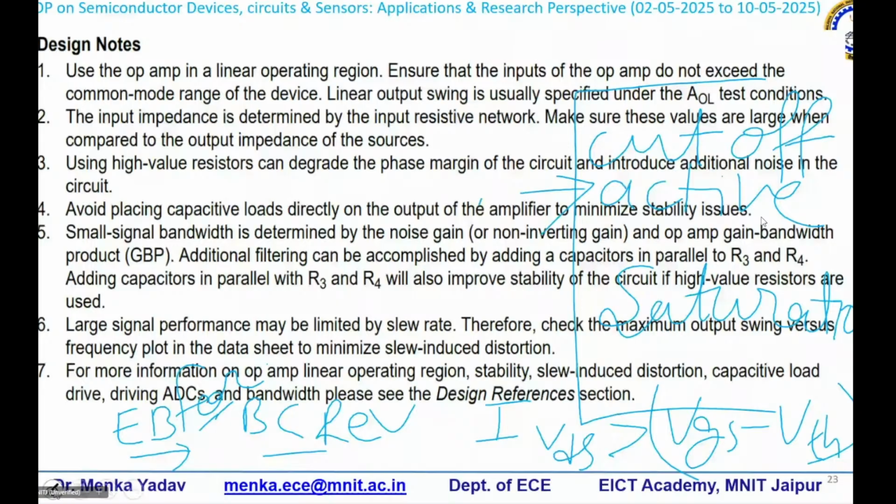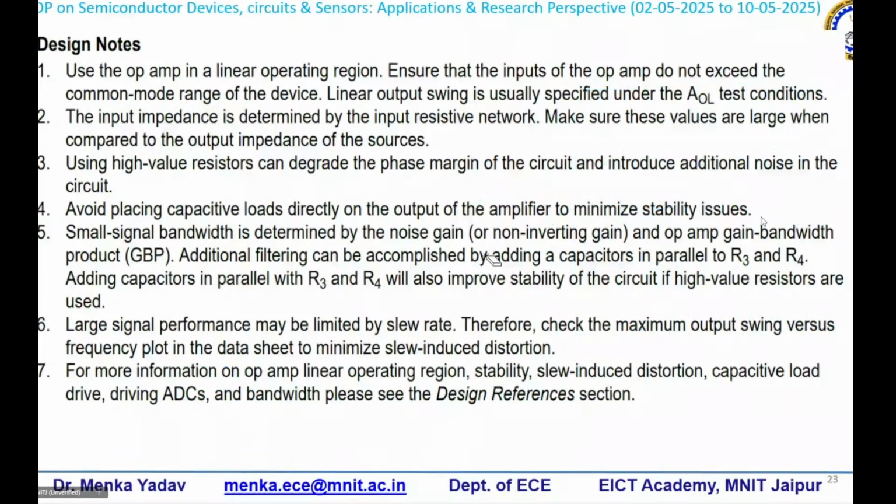So first of all, the first design step is to make sure that your device is working in the linear operating region, so that the inputs are not exceeding the limits of your op-amp.